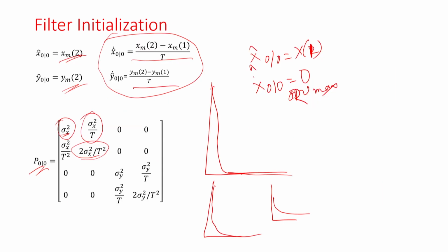This is very important, even for automotive radar and all ADAS applications, people do not prefer to use EKF or any non-linear filter, EKF, particle filter and all. Pseudo-linear filter is the best thing to use. So, this is one part of pseudo-linear filter, it is not yet over.